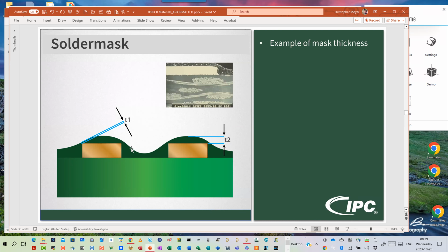and the solder mask in between here may extend high enough that if I'm trying to expose some surface mount solder pads, the part is no longer sitting directly on the pads, but sitting on this pedestal of solder mask. And then during the soldering process, the force of the liquid, the paste when it turns liquid, can pull one end of your chip resistor over, and the whole thing flips up on end vertically in what we call tombstoning.